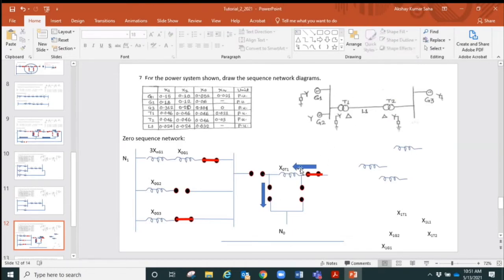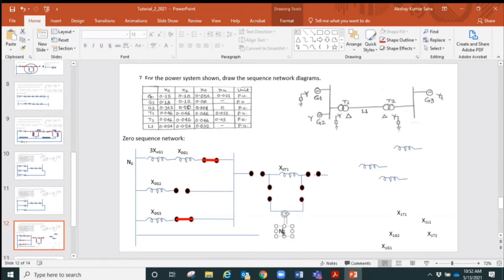And let's forget about these lines. For now, 4 of them are opened. Also, don't worry about those. I will check with those arrows for the determination of equivalent reactance if you want to do that. So X0, this one I forgot. This is supposed to be N0. You must make sure that all the labelings are correct. So this now transformer end connection now needs to go to the neutral of the system. So it goes to the neutral of the system, X0 of T1.